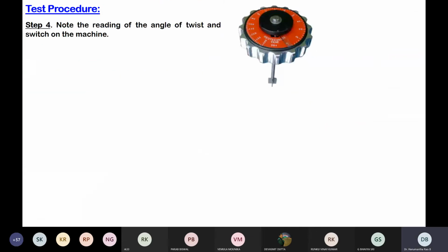Now, when you talk about any Vane shear test, the stress is applied in the form of a torque in a cylindrical form. Torque means cylindrical form. So this is the simple schematic which is connected to the scale and with the Vane shear. Therefore, you need to take the initial reading of the torque that is going to be applied. This is in the form of angles. The rotation is measured in the form of angles, or angle of twist.